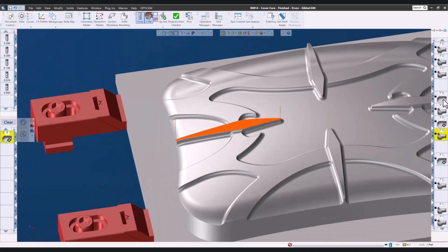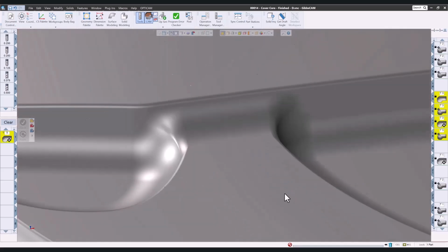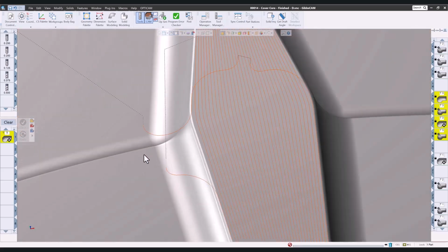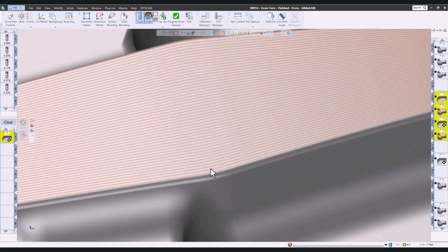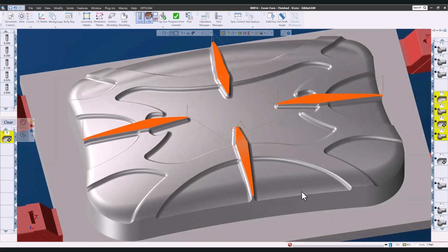You can see that all these options produce similar toolpath, but with varying numbers of retracts, although none of them have more than just a small handful. But they all start with one shape at one edge and morph as they move across the surface to the other edge.